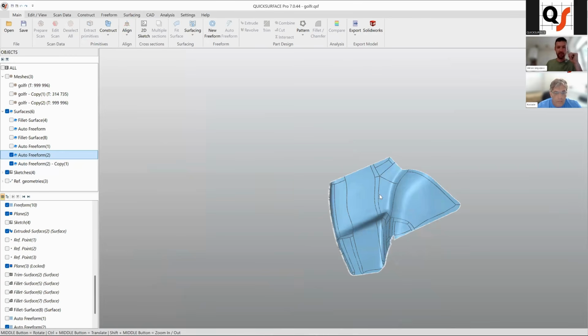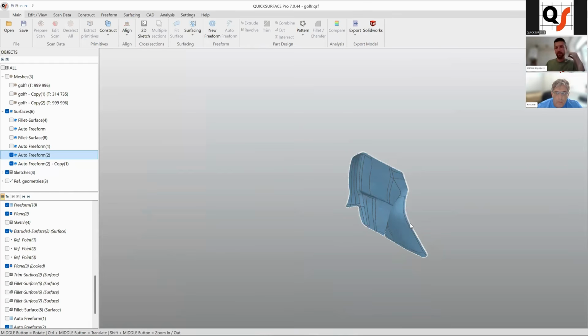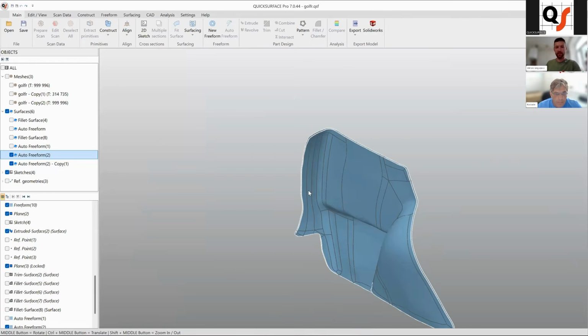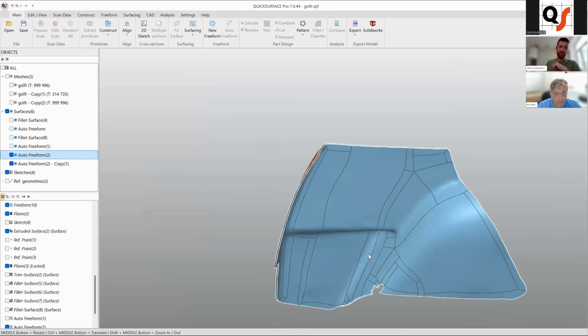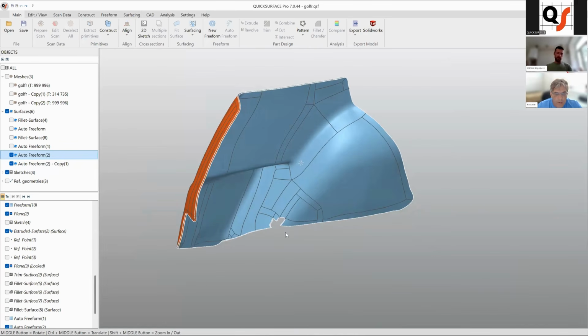Not just like thicken. Thicken may fail because of some sharper corners, super small surfaces that are being consumed due to the thickening. Then it will throw an error and it will fail. But in this case, you can thicken everything, well, almost everything. So this was just one more point. A cool part about the freeforms and flexibility.